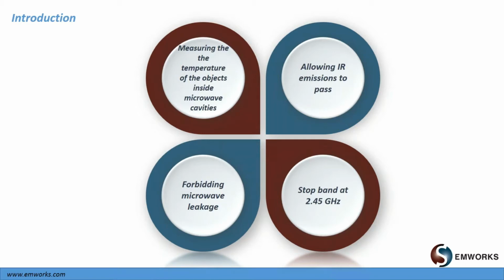So when we are heating something in the microwave, if we want to be able to monitor the status of the object, especially when we are using industrial microwave devices, it's important to find a way to measure the temperature contactless, because we're not going to be able to use thermocouples as the microwave is going to damage the thermocouple inside. So the best way is to use an IR sensor.